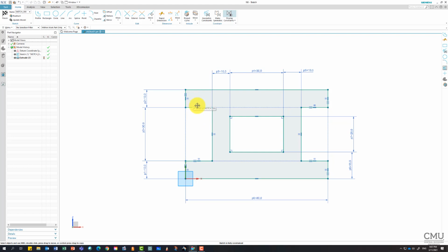Think about it, which one needs to be equal, which one needs to be coincident or collinear. There are a lot of handy geometrical constraints available in NX. Then after that, you can start adding or confirming the dimensions. Then you will be able to make your sketch fully constrained. So this is a key of chapter 3 and chapter 4.